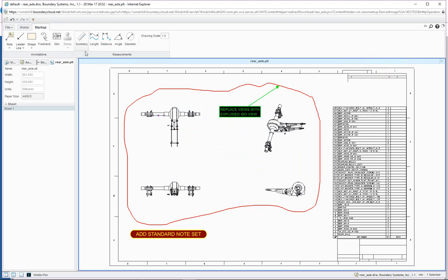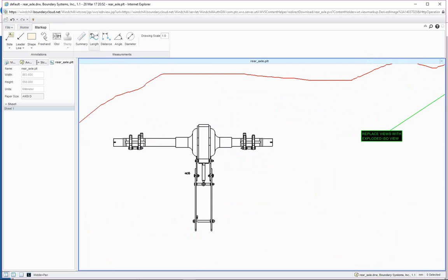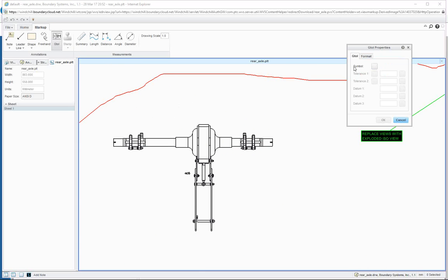All right. So I can continue to add additional information to this. Once again, if I want to specify any type of geometric tolerancing, I can do that as well. So if I want to add a GTOL, I can specify what type of geometric tolerance I want, true positioning, and then I can call out the actual tolerance values. I still have minimum and maximum, regardless of feature size type symbols I can add, and then once again, I can add that information, specifying the datum or datums that I want to use. Oops, sorry. So if I want to add any additional datums, I can.